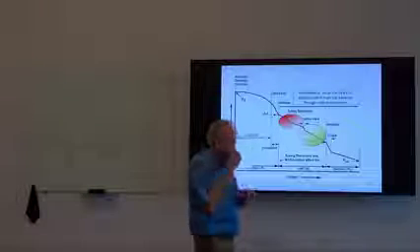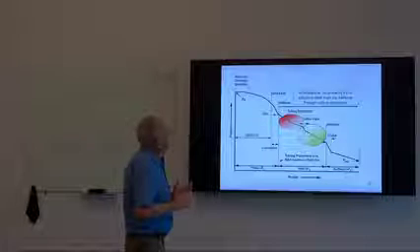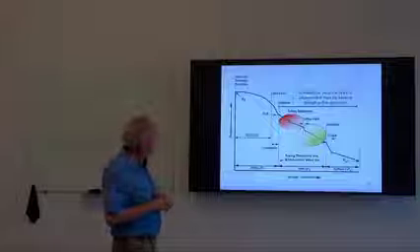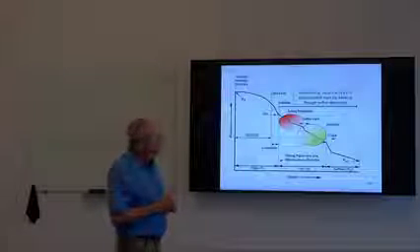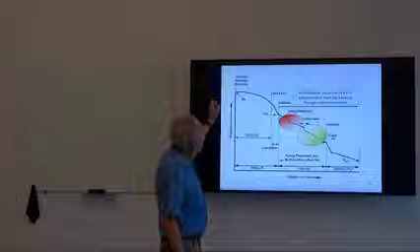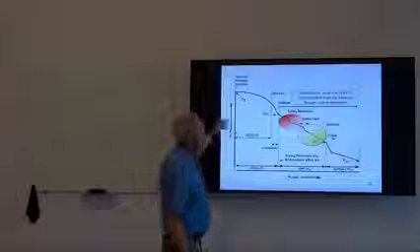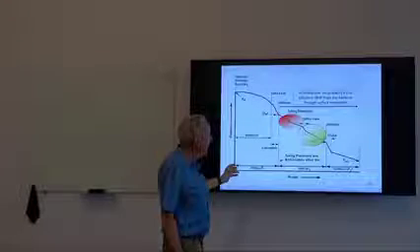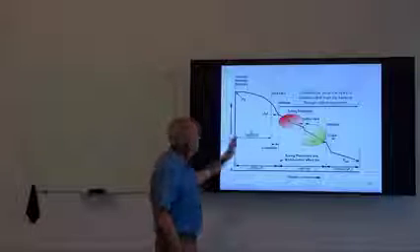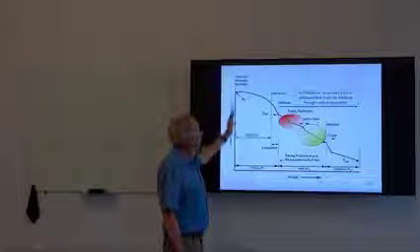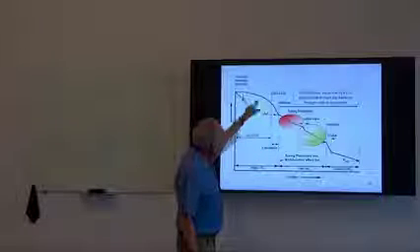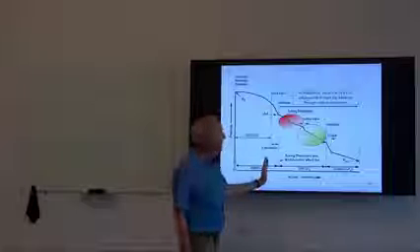This whole concept of pressure management is very, very important. This is a slide I obtained from Texas A&M, I believe. But in any case, it is looking at the pressure in the system on the y-axis versus its position in the system on the x-axis. We start out at some boundary of the reservoir, and this is our pressure drop across the reservoir. So we're moving position in this direction.